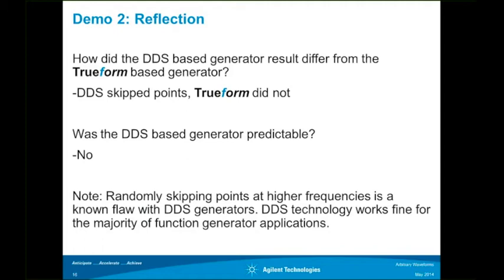I also wanted to mention that even if your waveforms don't show those missing points, so maybe you don't care about this lab as much, those missing points for arbitrary waveforms are going to manifest themselves differently for a DDS generator. Those missing points will show themselves as a distortion in your signal, or even increase the jitter in your signal as well. So if you are getting too much jitter in your DDS arbitrary waveform, that's going to be because of that missing point.